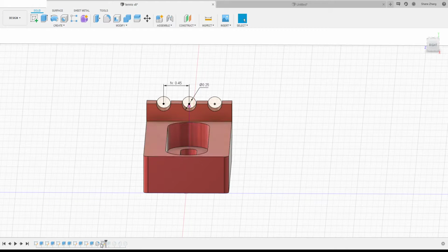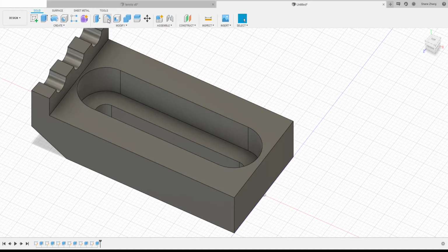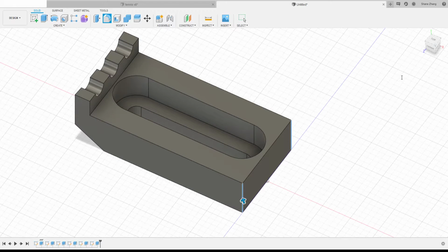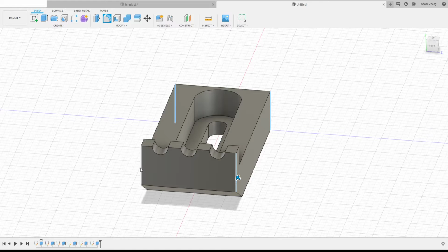find the dimensions. So before that, we actually have a fillet. This fillet you can do it last or right now, either way. So we'll see the dimension is 0.08. So we'll do a fillet, pick the edge, pick the other edge, the dimension is 0.08. And you can actually have multiple different ones. So if I pick two more edges, you could have different radius. So if you keep adding new selections, you can finish all the different radius fillets in one step. And sometimes it'll cause some kind of confusion.